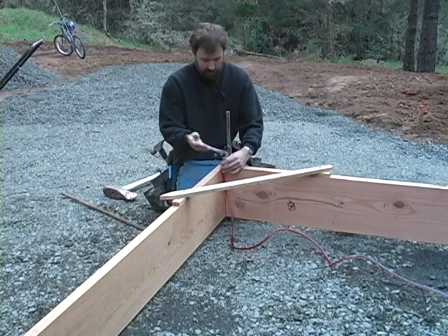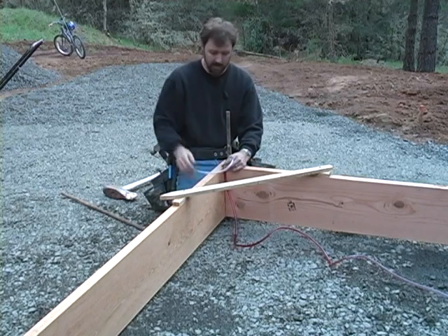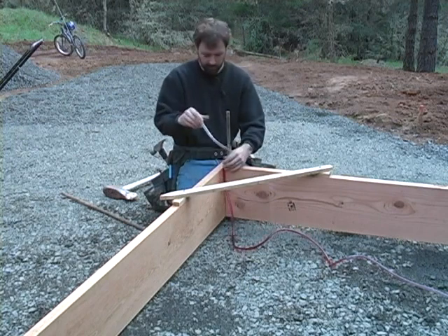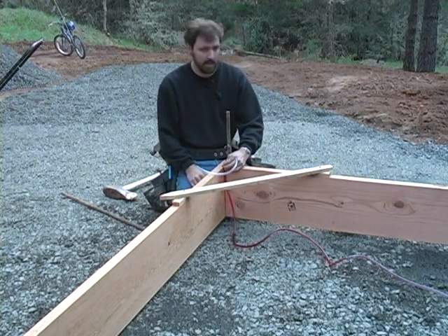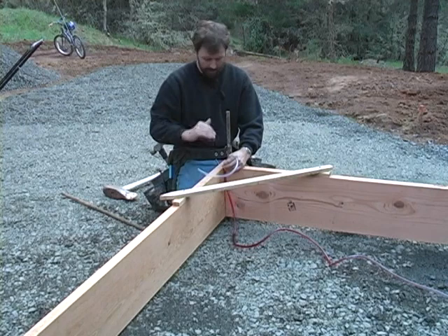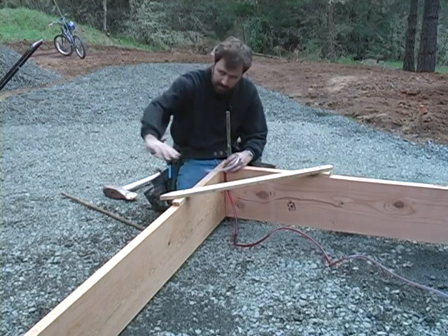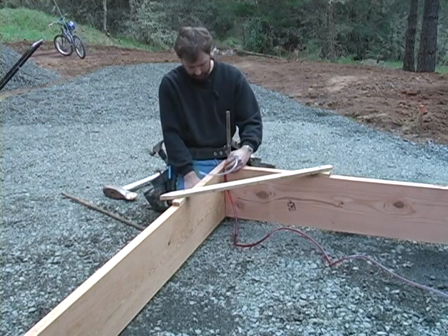This water level is a great way to level things over pretty good distances. This right here is a 50-foot piece of line, so it really does a good job at going a full distance and getting an accurate mark of level. Running a carpenter's level on the top of this wouldn't give us a very accurate measurement.